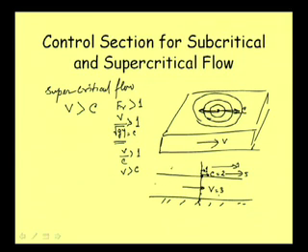So suppose this is supercritical flow, and the flow is coming. If you create something, that is not influencing this flow. It is coming due to some slope, due to some discharge here, and for this slope and this discharge it will flow as it is. This disturbance is not influencing this one.